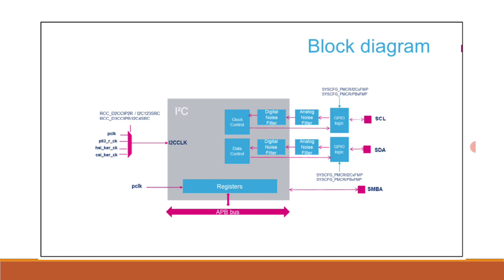The registers are accessed through the APB bus, and the register peripheral is clocked with the I2C clock, which is independent from the APB clock. The I2C clock can be selected from among the PLL, APB clock, the high-speed internal RC oscillator with a frequency from 8 to 64 MHz and the low power internal 4 MHz RC oscillator.